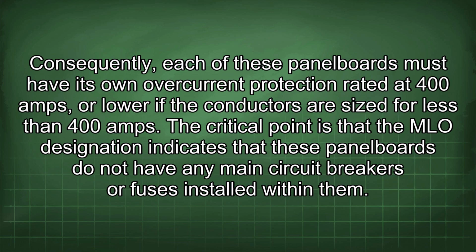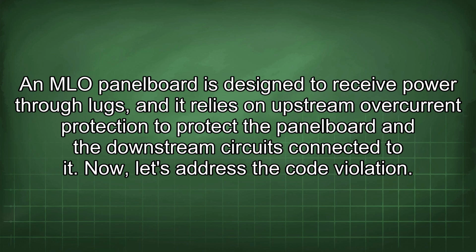The critical point is that the MLO designation indicates that these panelboards do not have any main circuit breakers or fuses installed within them. An MLO panelboard is designed to receive power through lugs, and it relies on upstream overcurrent protection to protect the panelboard and the downstream circuits connected to it.